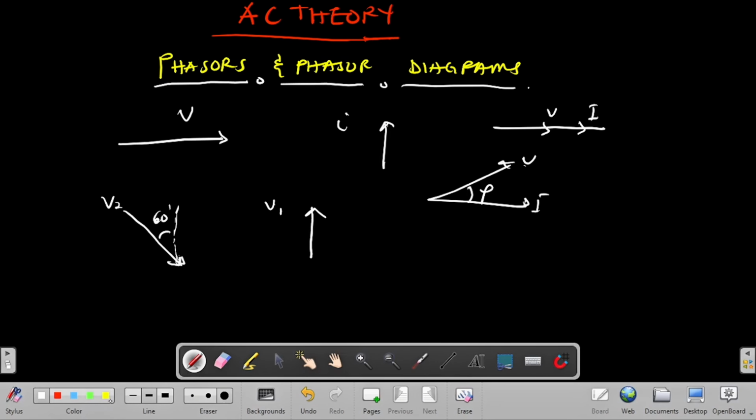To do this, let's see something here. I introduce an imaginary dash using the plane, so the angle here becomes 60, right? So this one is a perfect representation of V1. You can see, because V1 is a vertical one, right? So realize that our V2 needs to go anti-clockwise 120 degrees in order to assume the shape of V1, or in order to be in phase with V1. Therefore, we say that the phase difference phi is equal to 120. As simple as that. Or V2 is lagging by 120 degrees.